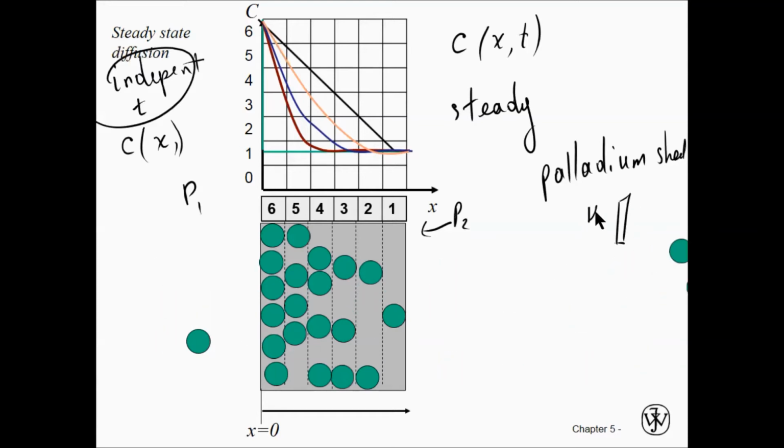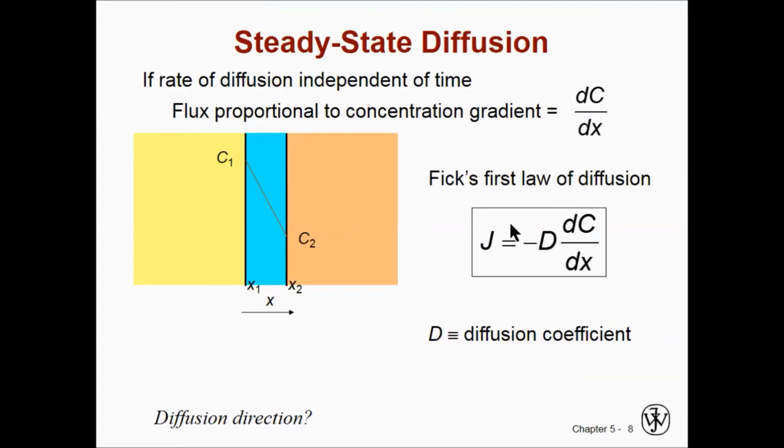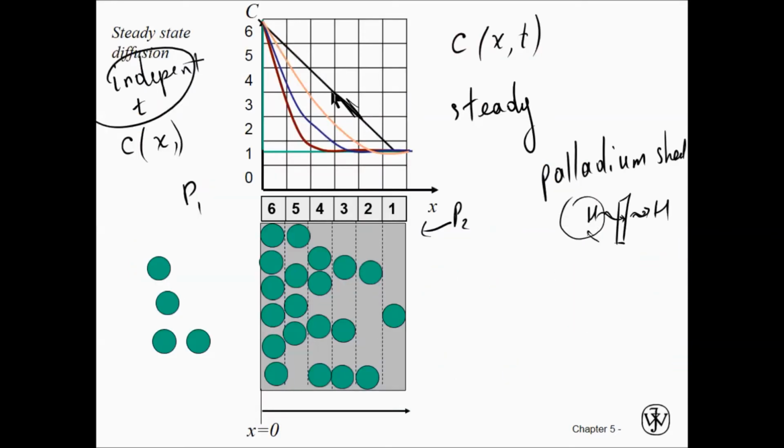They have a hydrogen gas, it will have some impurity, it is mixed with other gases, and this palladium sheet only allows hydrogen through it. As the impurity stays on the left side, what comes in goes out. They use steady state diffusion to purify hydrogen gas. Next, that's the line which we did achieve over here, this line over here.